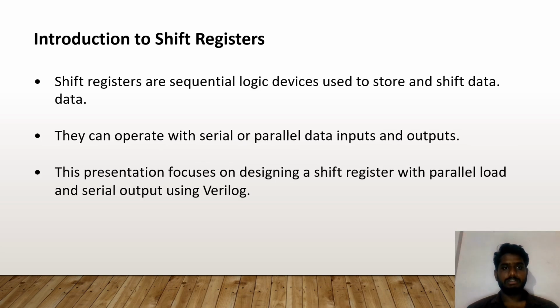Introduction to shift registers. Shift registers are frequently used logic devices to store and shift data. They can operate with serial or parallel data inputs and outputs. This presentation focuses on designing a shift register with parallel load and serial output using Verilog.